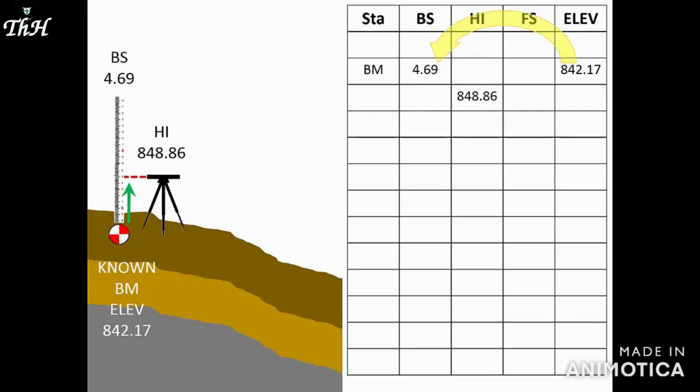When the backsight reading has been recorded, the rod person moves beyond the instrument operator to create a turning point. We'll start a new line below the one containing our first HI, labeling it TP1 for turning point 1. With the rod atop the first turning point, the instrument operator reads 6.08 feet for the first foresight. In the new TP1 line, we'll record 6.08 in the foresight column.